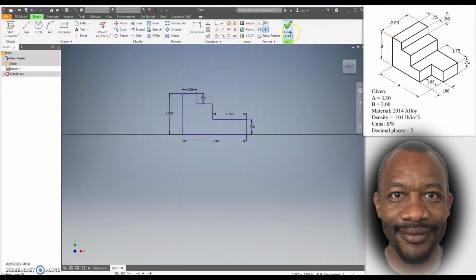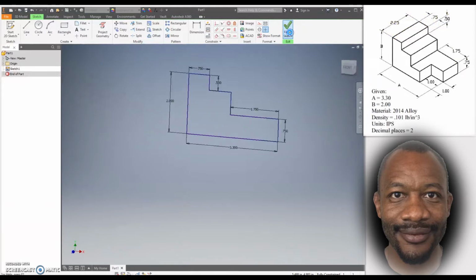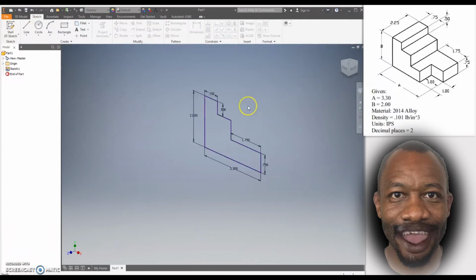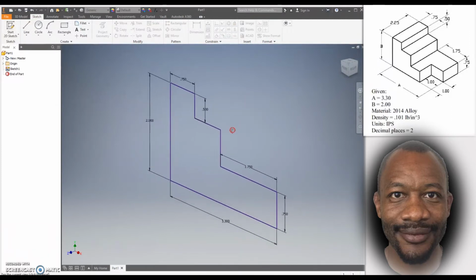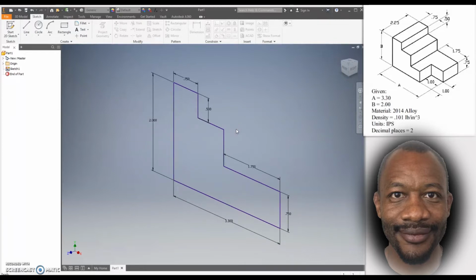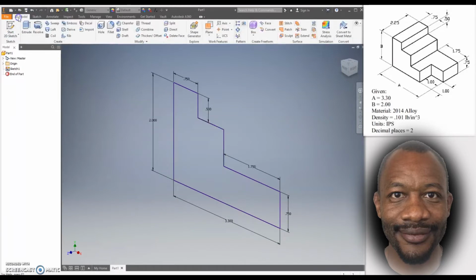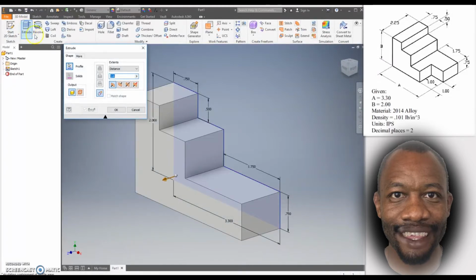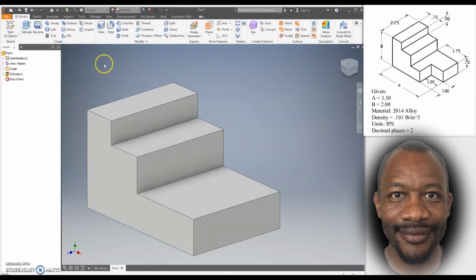All right, time to extrude this bad boy. Looking at the drawing, we have an extrusion of 2.25 inches. So we finish sketch, and we go to 3D model. Select extrude. Since this is the only sketch we've created, the only option we have is to create a new solid. In the future, we'll have the option to join, cut, intersect, and so forth. We type in the value of 2.25, we hit enter.